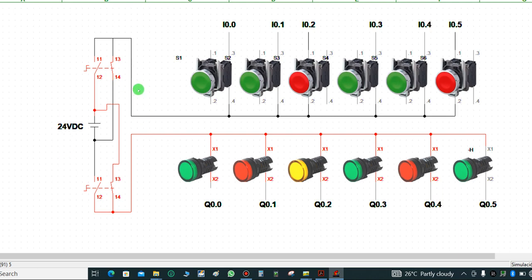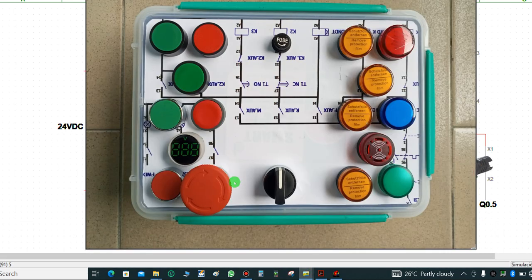So you're going to do this with your workstation so that whenever you go to any PLC, you will interchange sourcing and sinking with your workstation. Whichever one is applicable to your PLC, you just activate the switch to switch from sinking or to switch from sourcing. Okay, so your workstation should be compatible with sinking connection and sourcing connection. So this is how to create your own workstation.